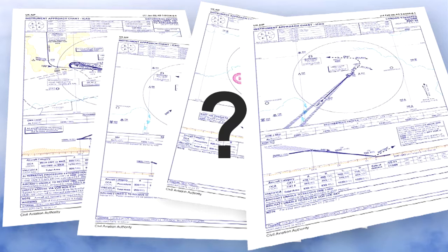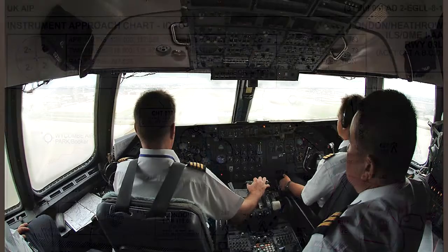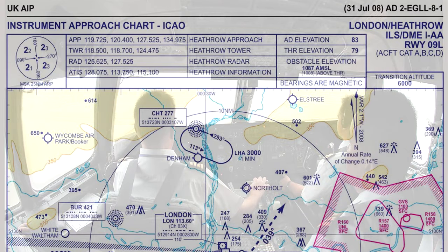Should a pilot be unfamiliar with any particular approach, the specific reporting points will be specified to him by the Air Traffic Service Unit. Should visual reference to terrain be established before completion of an IFR approach procedure, the procedure must be executed in any case unless the pilot in command requests and is cleared for a visual approach. Sometimes a particular aerodrome approach is specified to expedite air traffic, but the omission of any specification will indicate that the pilot in command may use any approach procedure that is authorized for that aerodrome.